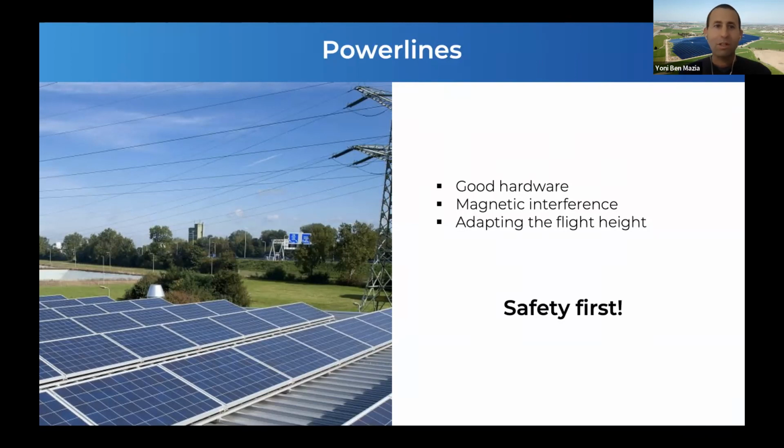Like everyone mentioned here, the tactic to mitigate that is either splitting blocks east and west, or northwest according to the power line, or using a drone that can fly over it. I think with the Matrice 300 H20T, you can fly at 50 meters with the correct GSD and overlap needed, and I don't think the power line would be 50 meters high. So you can keep a safe distance and do a consistent flight, no problem.